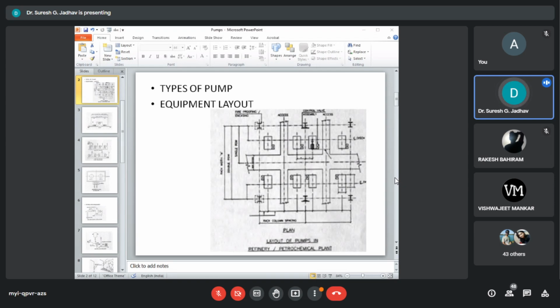The size of this foundation shall be approximately 500 by 1500 millimeters, or can vary up to 20,000 millimeters long in the case of large pumps. Large capacity water pumps usually have horizontally split casings. Inlet and outlet are horizontal at right angles to the pump.